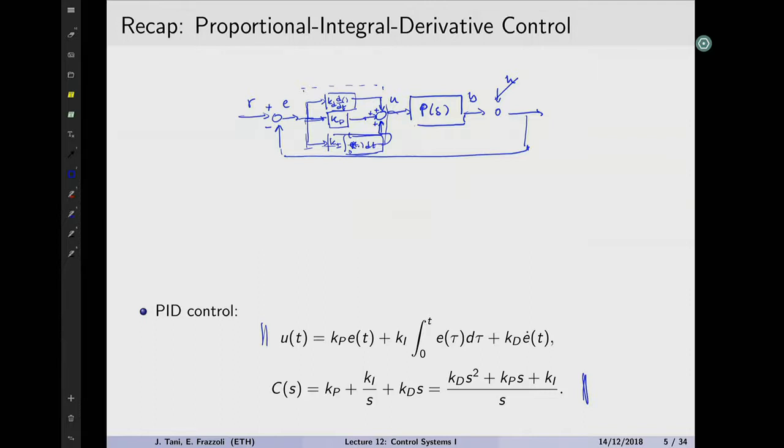You saw that this was a very effective strategy, and it is important to see that this is an output feedback control strategy. The control input is proportional to the error, which is a function of the system's output. I stress the word output as opposed to the system states. We mentioned throughout the course that the states contain a lot of information about the system, and if we know the states, then we can do some pole placement, not the ideal control, but we'll see this later on.